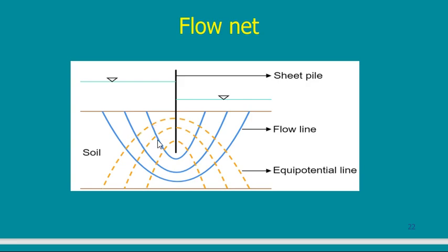Look at these four lines. If I start with this middle point and this middle point and this middle point and this middle point, I can put a circle in this space. So in my drawing, I should always keep in mind, suppose that you draw this one and you want to draw the other one, if you take it here, you will never draw a circle, you will draw an oval. So the circle will always tell you the distance where to put your next equipotential line.